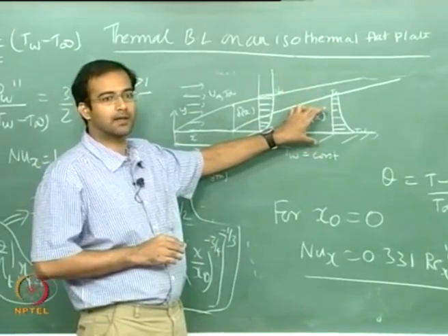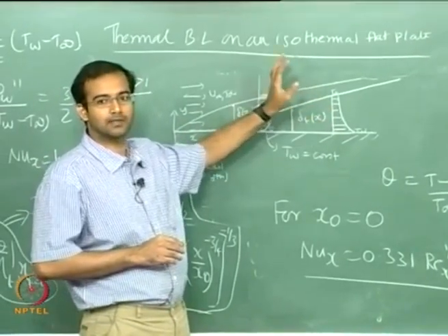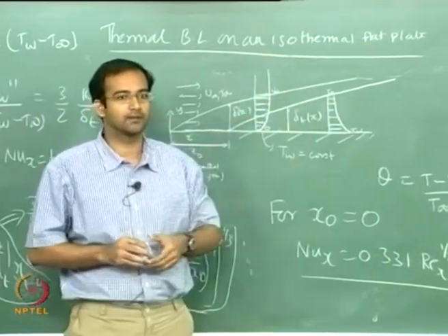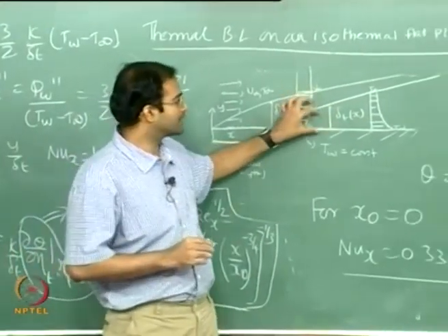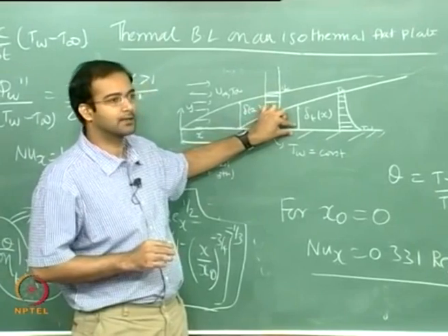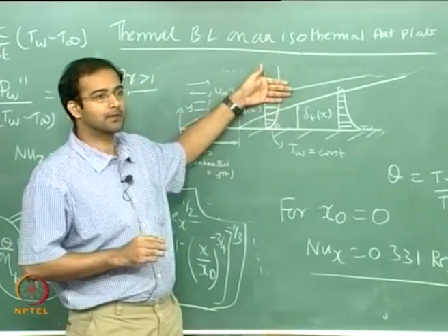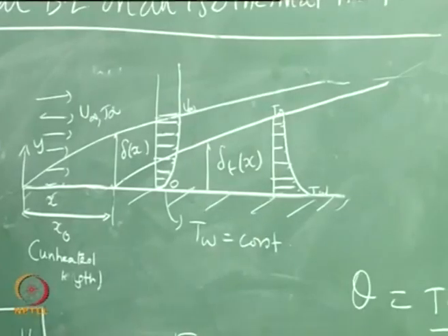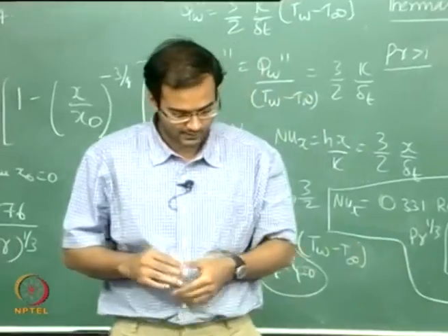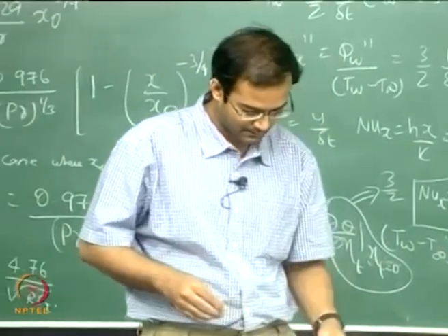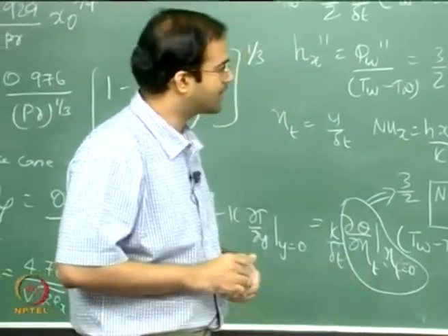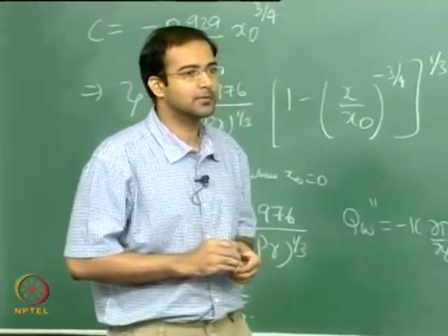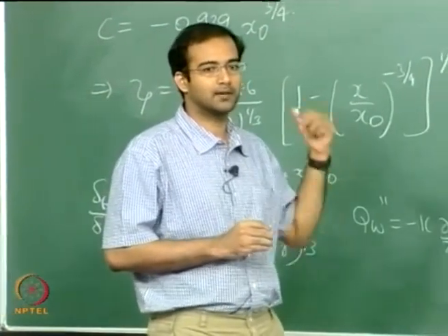So you can make a uniform velocity approximation rather than substituting a profile, since the velocity boundary layer is so small that most of the thermal boundary layer sees a uniform velocity. That is a much simpler case, and I will give you that as a homework assignment. In the next class on Tuesday we will look at flows with pressure gradients, where we can apply the approximate solution.